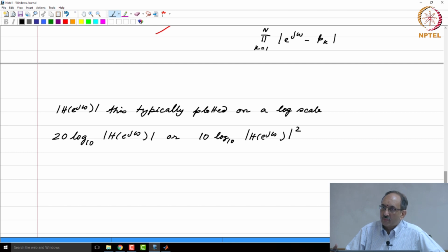So, one is say 30 dB rejection, the other is 60 dB, and if you plot this on a linear scale, in the pass band the gain will roughly be 1, and in the stop band you will not be able to see the difference between these two responses. If the pass band gain is 1, the stop band will look roughly 0, but you will not be able to see the difference between these two filters.